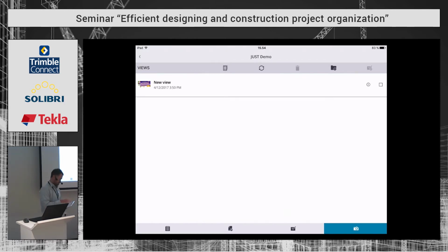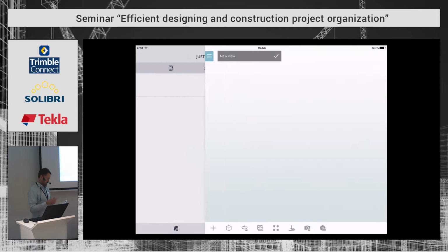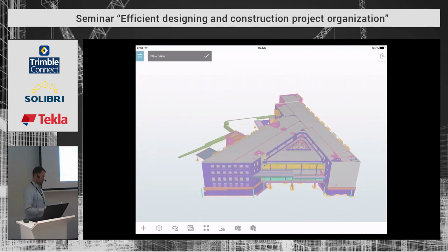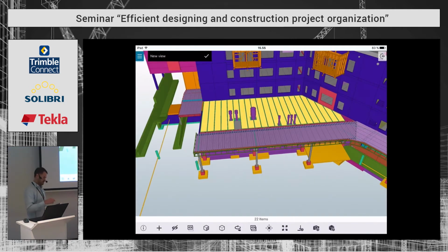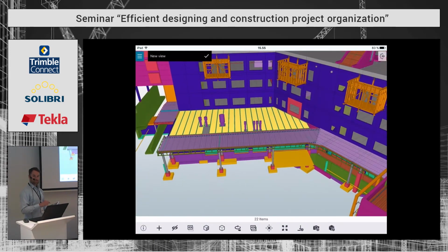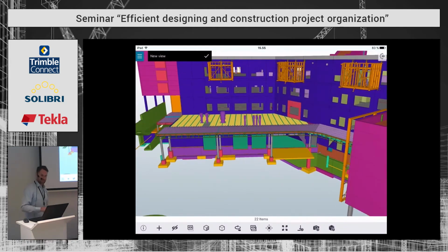This was the installation plan, and when I open the view, it will open the file that is related to this view. It could be that several files are related. Now it's a couple of models that it opened, and it selected all those hollow-core slabs that were planned to be installed. Does this model include rebars? No, I have rebars, but now it's only concrete elements, precast elements, and cast in place here. But you can open rebars also.